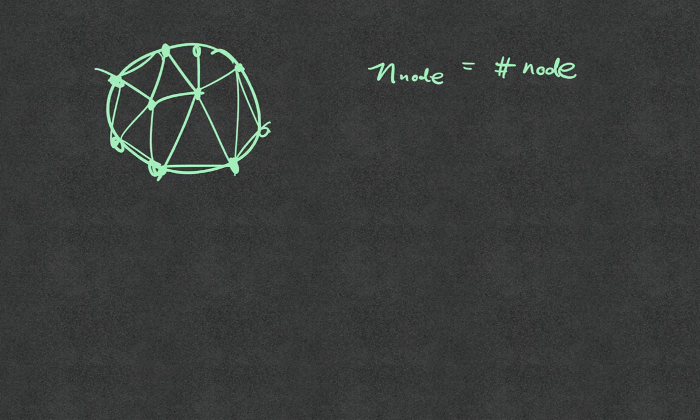They also carry the coefficients of our function, the function that we want to express. For the governing equation we have, our degrees of freedom per node is equal to 1. This could be important for your global assembled matrix, but here let's just make it very simple. So it is equal to 1 because h is the only unknown.